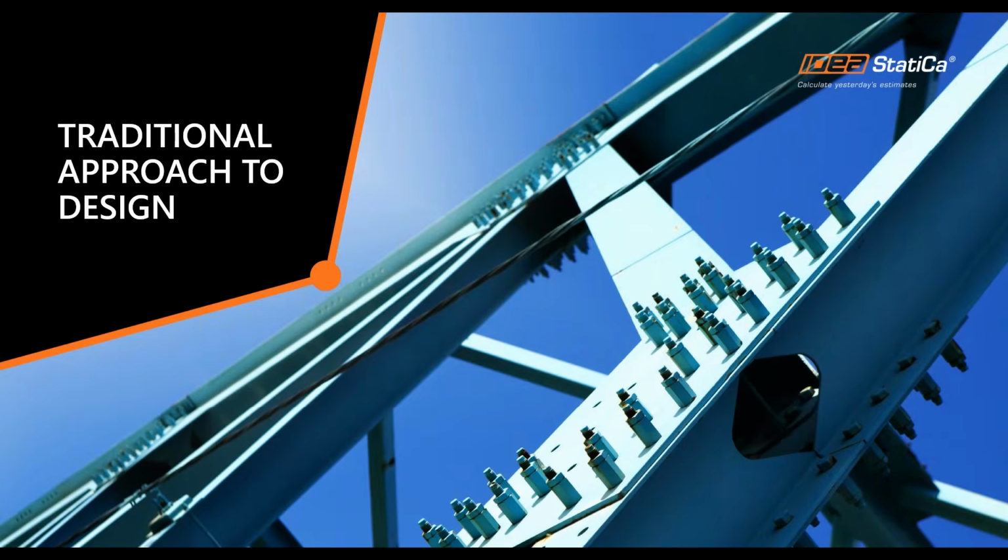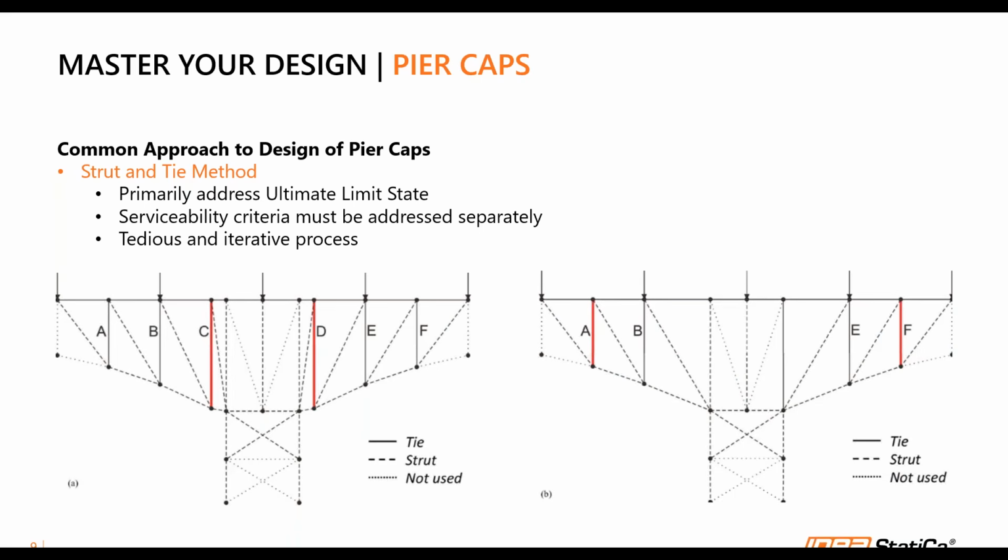So for the traditional approach to design of pier caps, one of the very common methods to design structures with, for example, pier caps is the strut-and-tie method, the one that most of you selected. While this has been proven over the years to be very effective in addressing ultimate limit state, this method is, as you all know, very iterative and can be very tedious to work on.